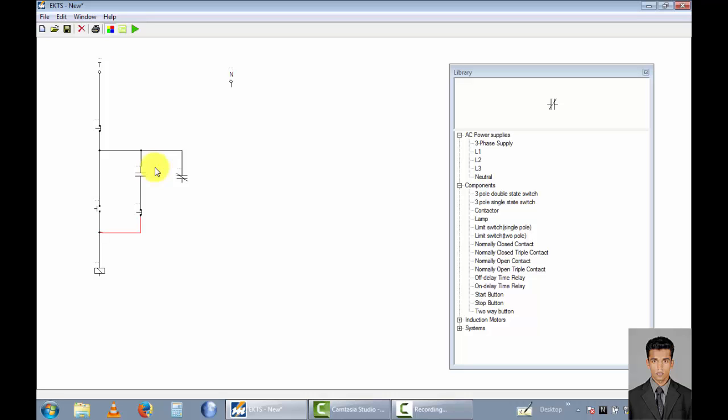and I want the other two contactors. So I want 1, 2, it take to this point, and the other take to this point. Okay, now I want a normally closed contact point for the K3 contactor, and rotate 90 degrees, and I combine this terminal to this one,